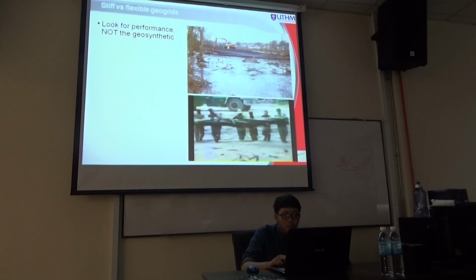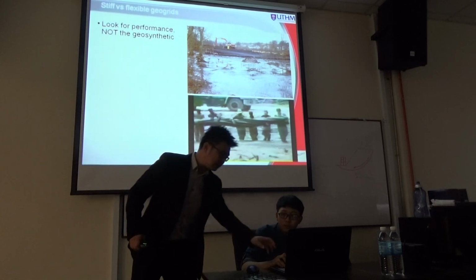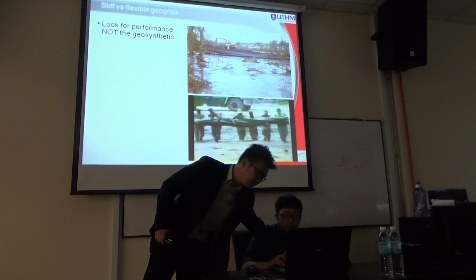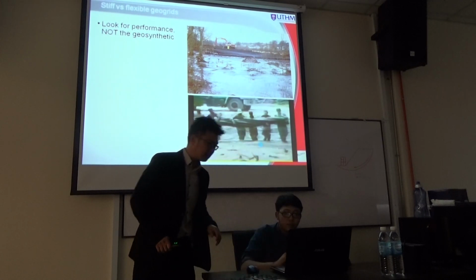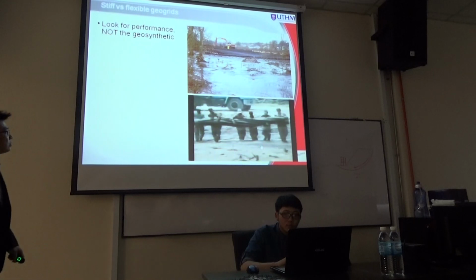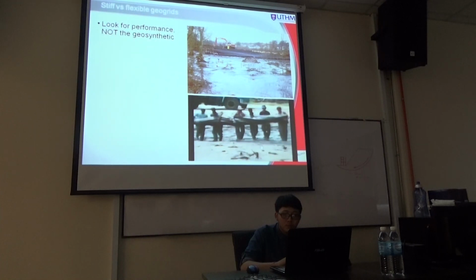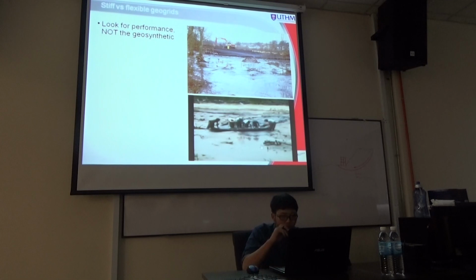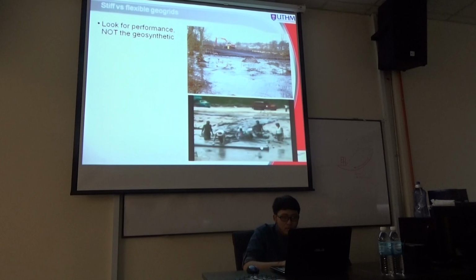So as far as this video is concerned, later I'll play a video for a short while on this part. So you can see that this group of people is taking the woven geotextile, trying to stabilize the base here before they do the backfilling on this swampy area. So they are trying to walk into the site and do the installation. You see how difficult it is for them to do the installation. Even when they unroll it, they try to step on it, but they still sink.